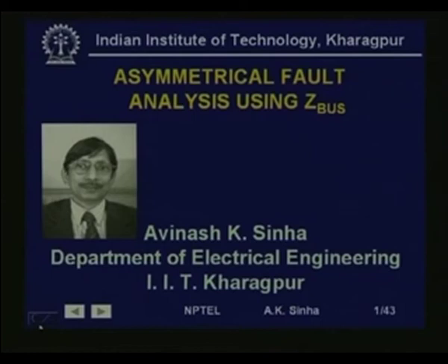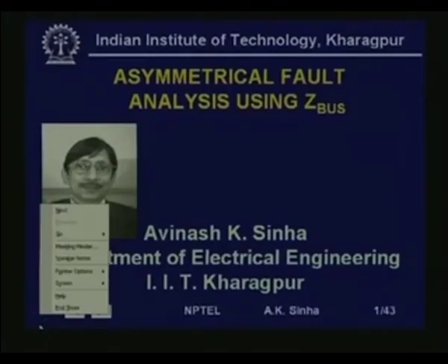Lesson 32 on power system analysis. In this lesson, we will discuss asymmetrical fault analysis using the Z-bus method for large power systems. As we had discussed in the earlier lessons, we have seen how we can use the Z-bus algorithm for solving symmetrical faults for large power systems. In this lesson, we will try to extend that method for solving asymmetrical faults.